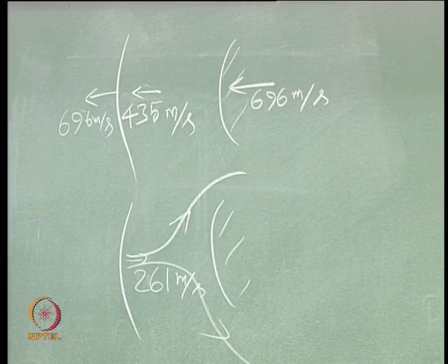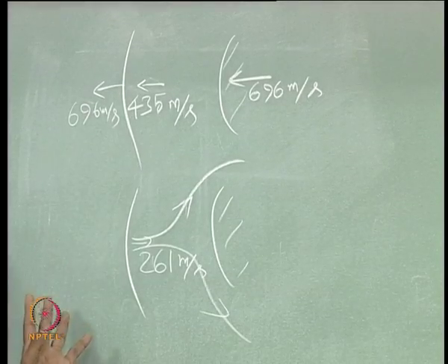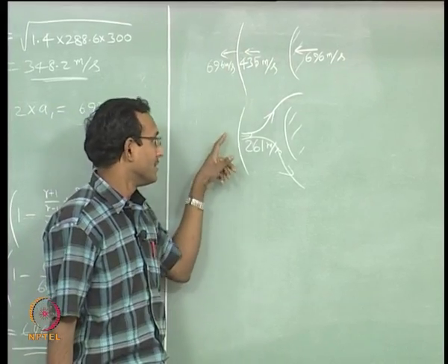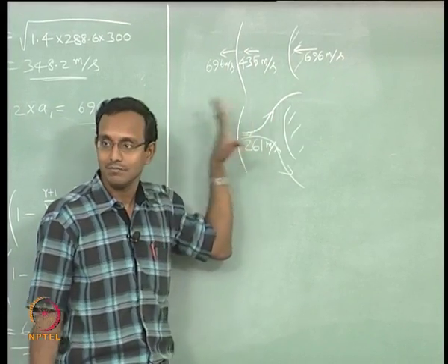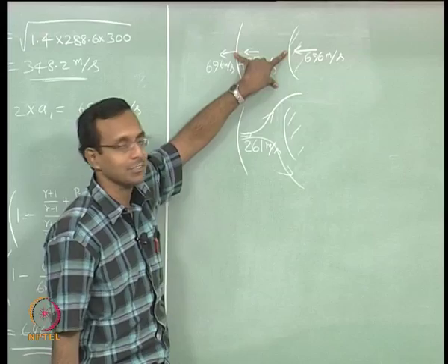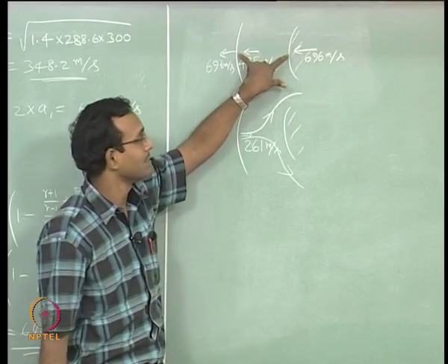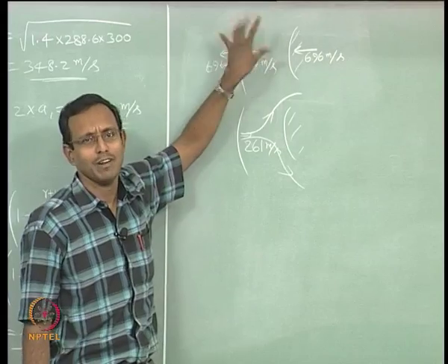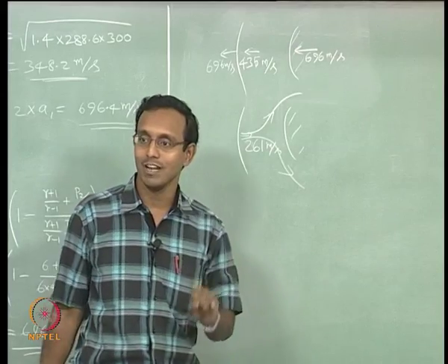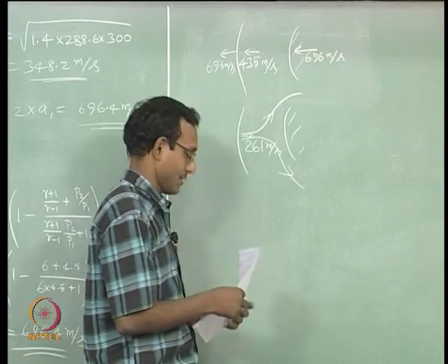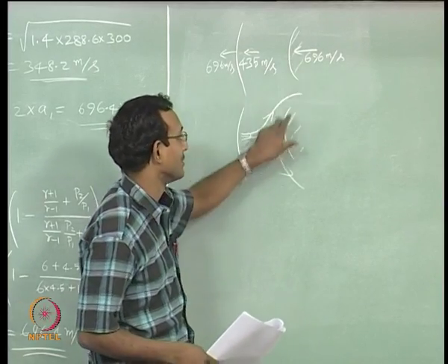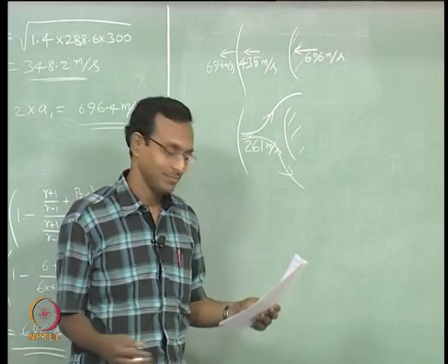Okay. That is why you have to get used to the problem from both points of view. Whichever reference frame I am in, I should be able to solve the problem. Okay. The shock is such that this flow around the problem will give you a steady state. Okay. It so happens that shock will stay stationary at some particular distance from the body. There is something called a shock standoff distance. We will not deal with it now, we will deal with it when we have bow shock. We have not gone to bow shock, we are still in normal shock and moving normal shock, that is what we have done till now. Okay. And shock standoff distance is decided by how much mass flow rate has to go through and turn around the cylinder, is it having enough space and all that.